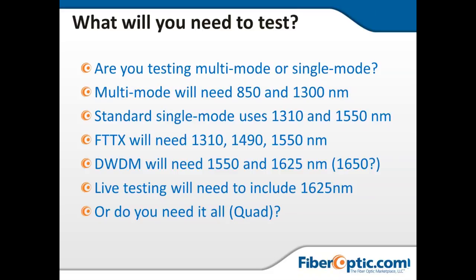And then the 1550 nanometer wavelength here is what is reserved for what's called our RF signal. For our television signal, a lot of those original television signals came with RF, so it's RF over fiber, and those were transmitted at this 1550 nanometer wavelength. So if you have a fiber to the home where it's using RF over fiber, then you would use that 1550. If it's IPTV, then you might not need that 1550 wavelength, and you might just be operating at 1310, 1490. So just something to take into consideration if you've got a fiber to the home application: do you need to consider that 1490?